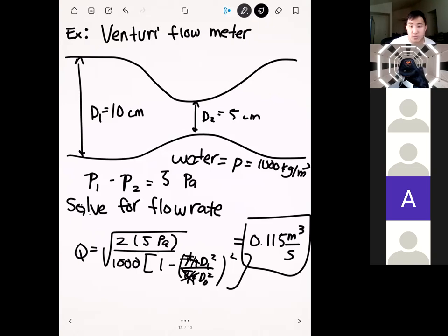Okay. Any final questions on Bernoulli? Okay, so that's all we got time for on Bernoulli. So hopefully what you've seen here is that Bernoulli is a very powerful tool, just because it's a relatively simple equation, and you just apply it between two different points. But I want you to always remember the restrictions on applying Bernoulli. So remember that we have our 4 assumptions. In order to apply Bernoulli, our flow has to be incompressible, it has to be inviscid, so there's no viscosity, it has to be steady, and it also has to apply along a streamline. Bernoulli usually is your first step for analyzing fluid dynamics, but it's important not to abuse it. So remember those four conditions on how to apply it.